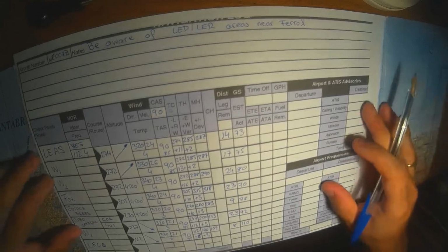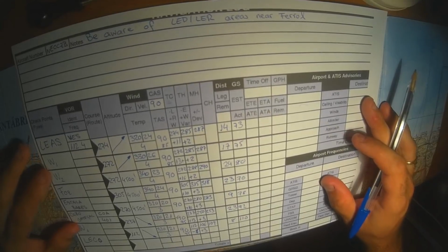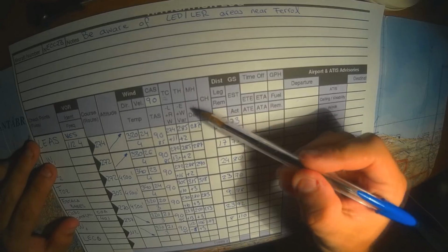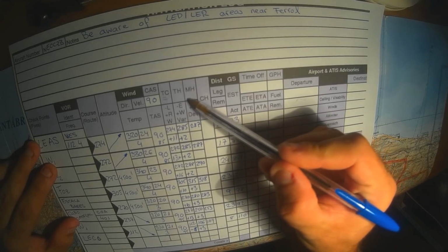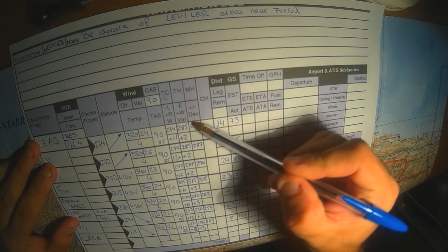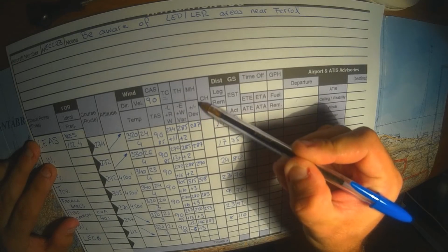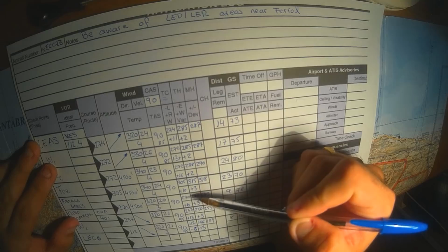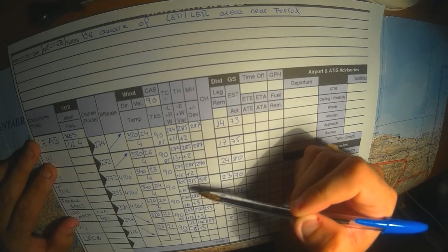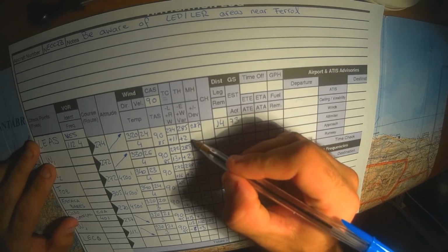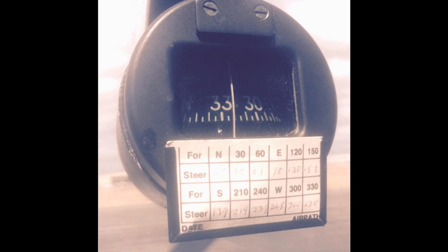The compass heading is also affected by the behavior of the compass itself. The compass can malfunction or work improperly due to magnetic, friction or G-forces, other elements or instruments of the aircraft, the building and structure of the compass, etc. All these errors are known as deviation and are usually represented just below the compass on what is called the compass correction card.